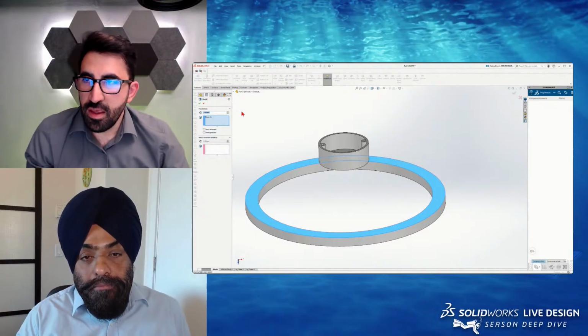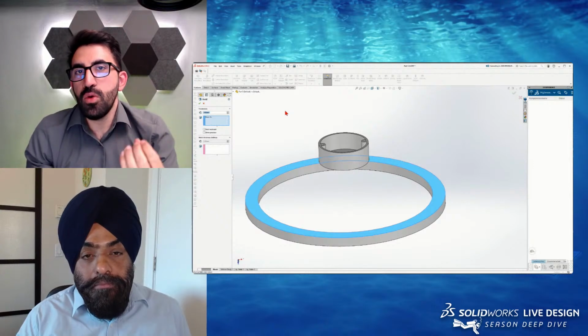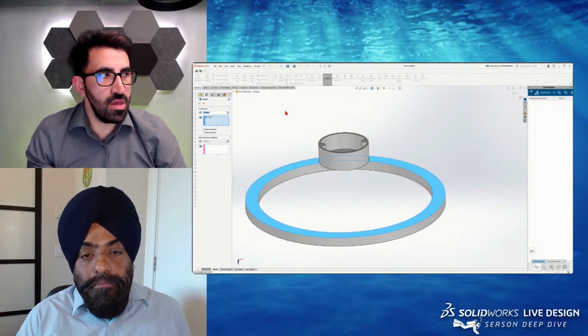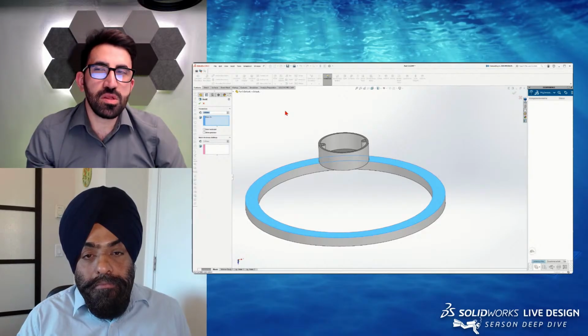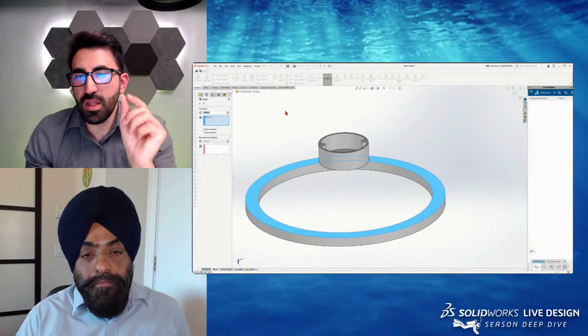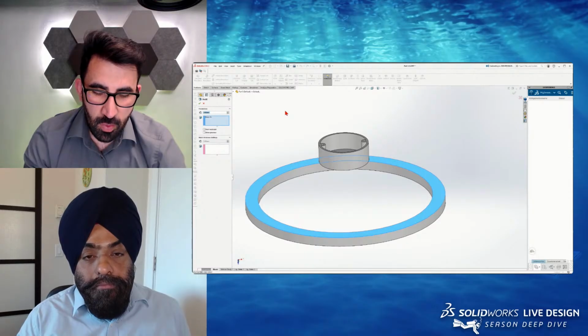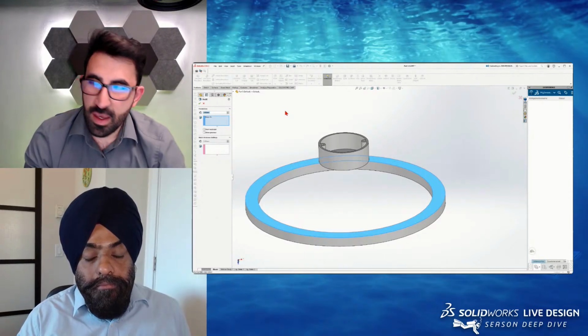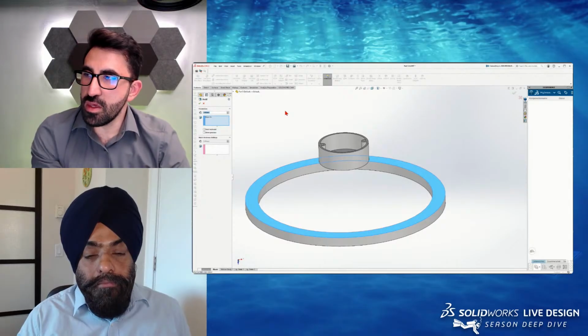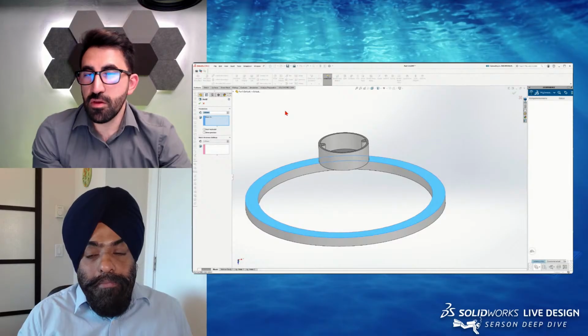Good, that's fine. Now, one factor that comes to mind after knowing that we are going to 3D print this is how strong is our material? Like if I shell this with a thickness of 1 millimeter, which is really low, by the way. I'm just doing this for those who are used to work with the imperial system. I don't know how accurate you can see this, but this is 1 millimeter, and this is very thin.